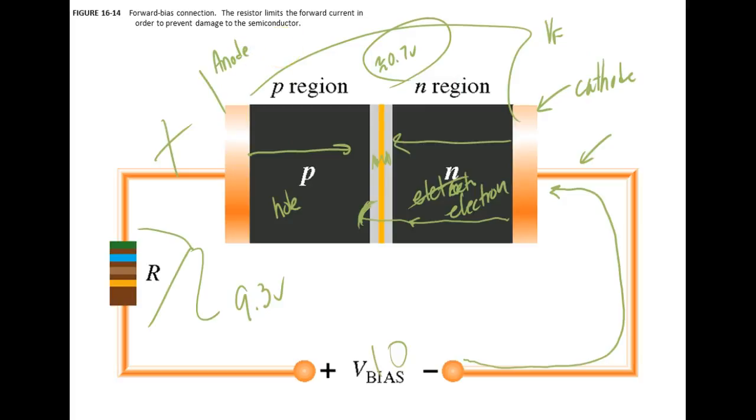So to forward bias a silicon diode, you need to have the cathode 7/10 of a volt less positive. It can be more negative or less positive, right? You understand? A lot of people say to forward bias a diode, the P has to be positive and the N has to be negative. That's totally false. You'll probably never see that.